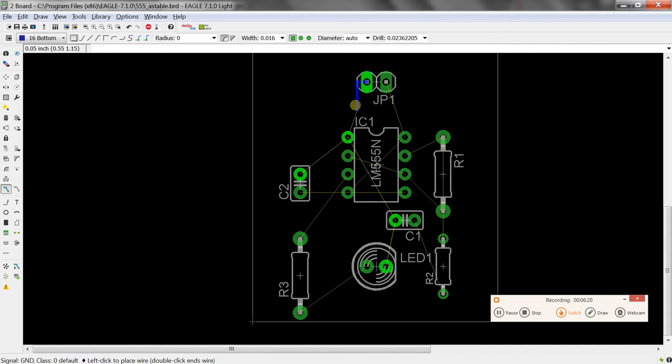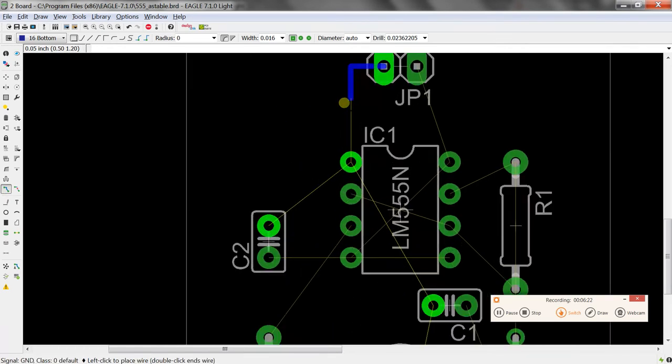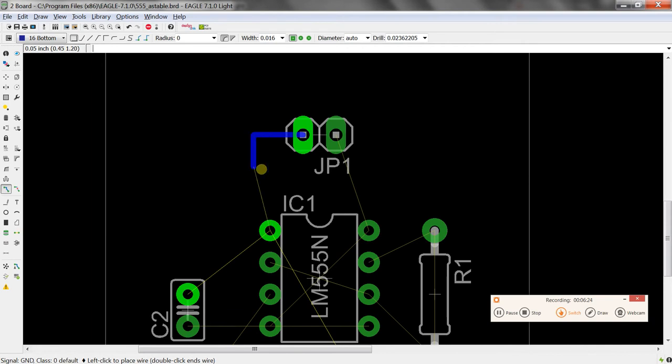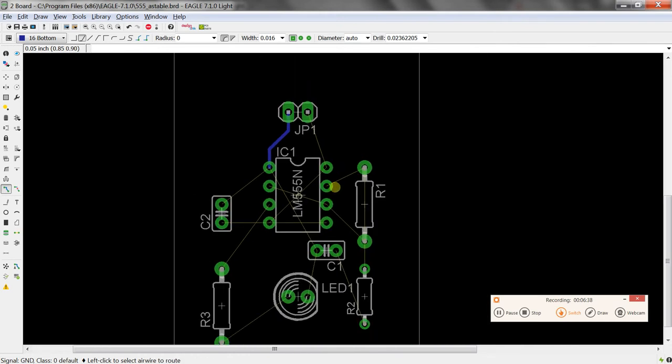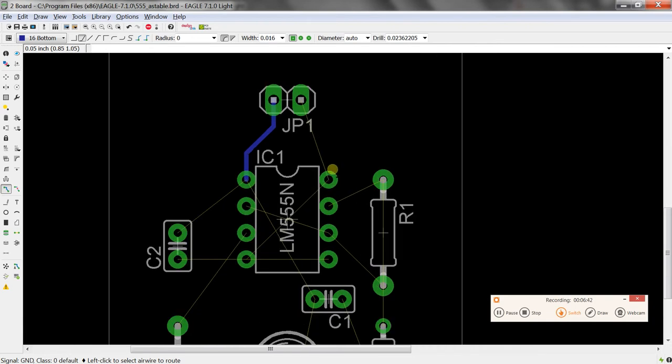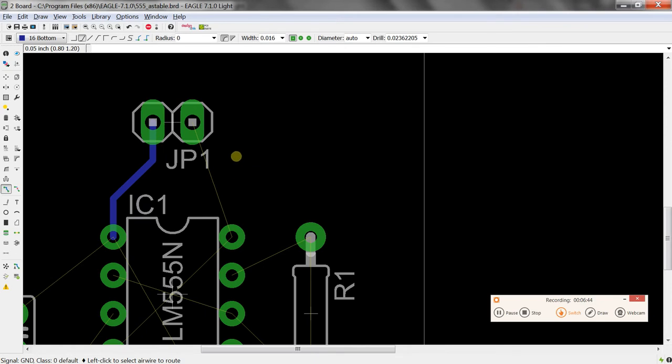Now always, PCB design guideline, never have the tracks 90 degrees to each other. Instead, if you right click, there are options that come. Never have it at acute angles or 90 degrees as much as possible, because that creates excessive current flow or excessive heat generation because of sharp turns that the electrons have to essentially follow.